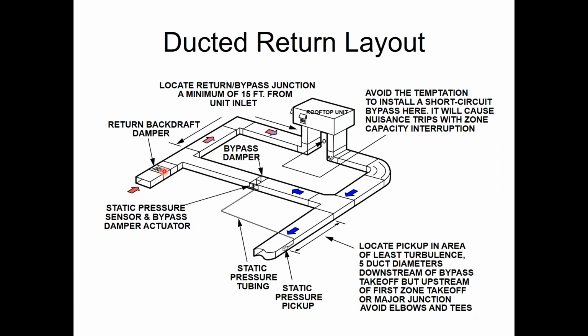Well, the zones that are close to the air handler are not going to be open, so the room's not going to be pressurized, so the return duct's not going to be pushing air back into the return. So when this bypass opens, some of that air could go backwards into those close zones, and that could cause dumping on people's heads. It's not a normal thing that happens, but every once in a while it will. It's better to have the zones farther away if you can.